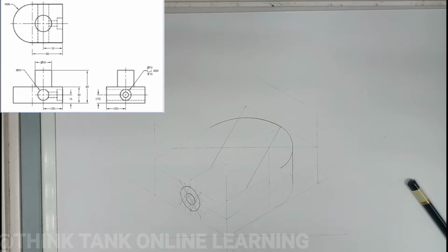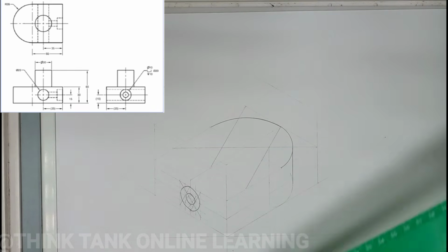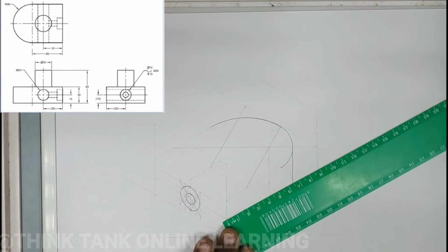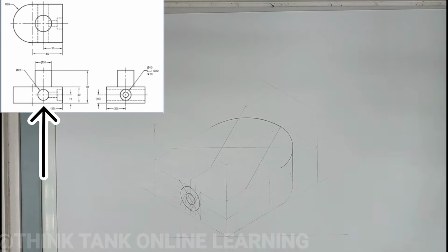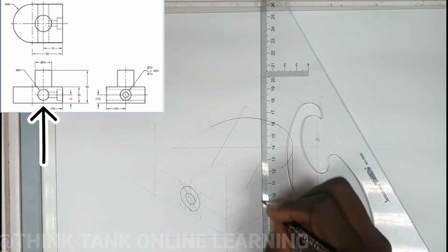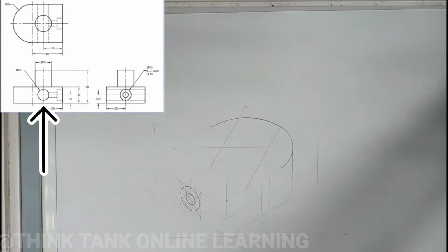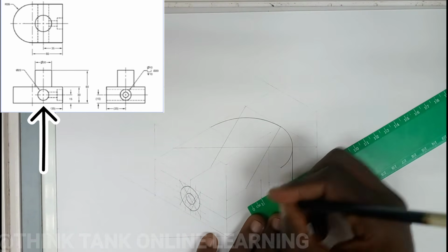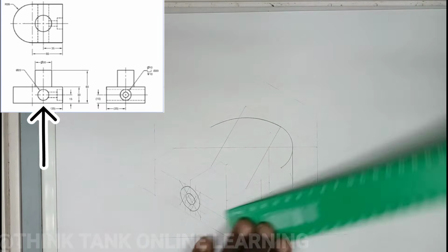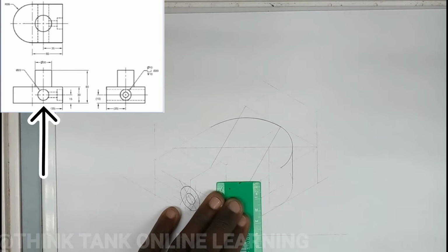Okay, now you have your two circles, so only left with putting some center lines. I'm going to draw another circle that is 35 millimeter from the edge. So here, bring my things upwards. Okay, and that circle is a radius of 10. So I'm going to draw another square which are size 20.